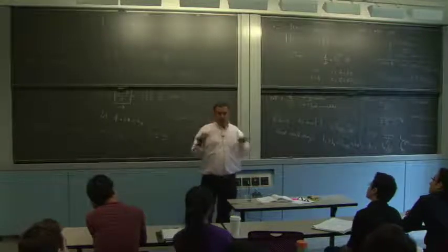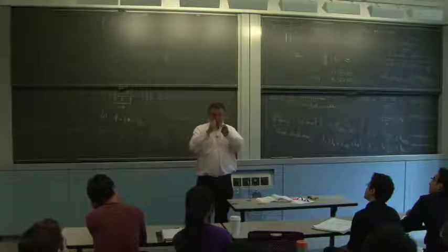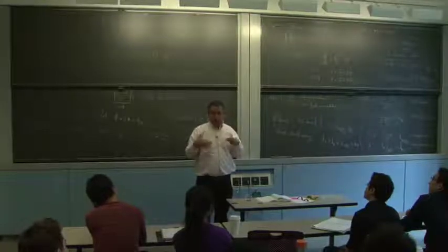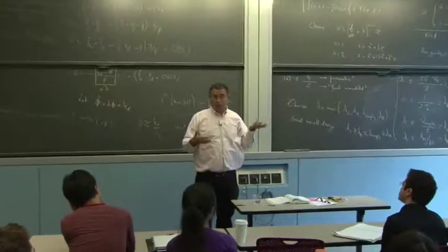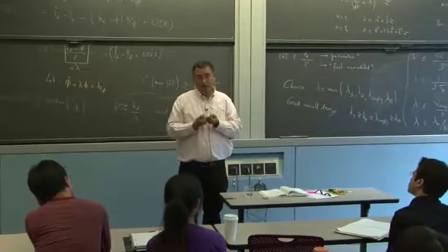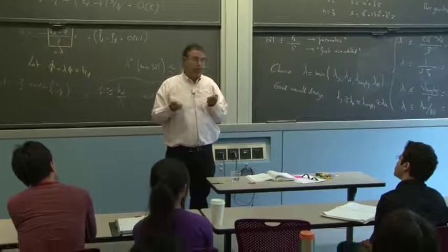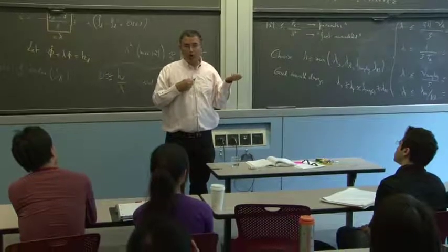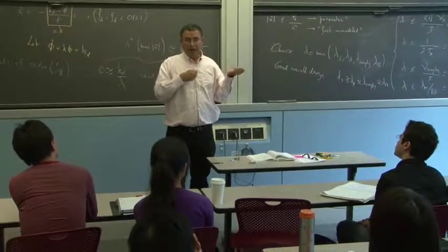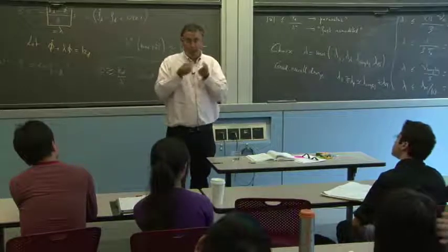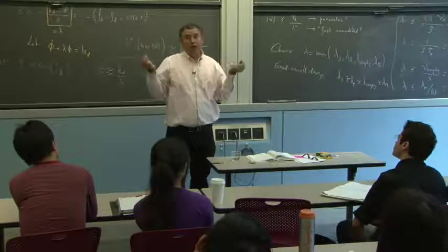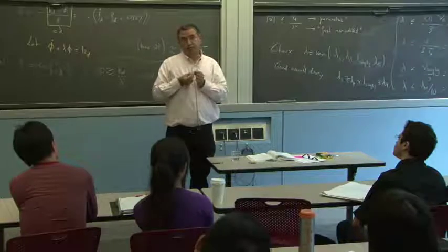So we will see that in that case, when part of the uncertainty is due to constants, you can go further than just this robust control. You can add what's called adaptation. And adaptation basically will make the system work as if, in the system model, in the F, the unknown constants were known.